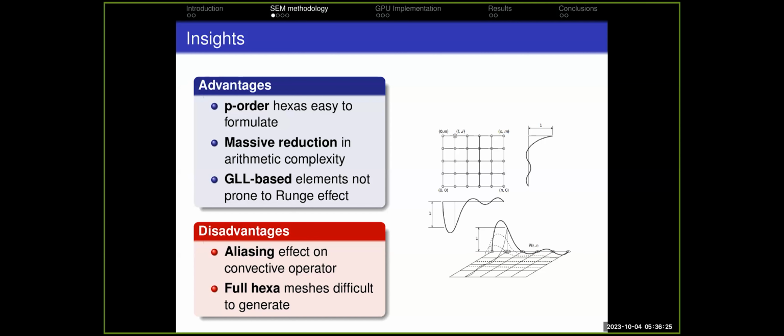As in the picture to our side, this is not exactly what a spectral element is. This is just a Lagrangian element, but it gives an idea of what I'm talking about, where a shape function of a node is the product of two Lagrangian polynomials at that node. So a node can be decomposed in its i, j, and in 3D, k components.